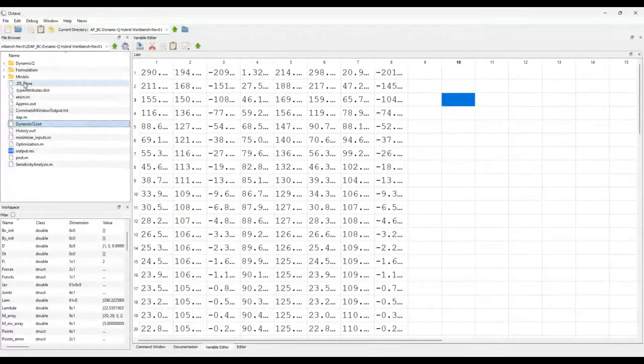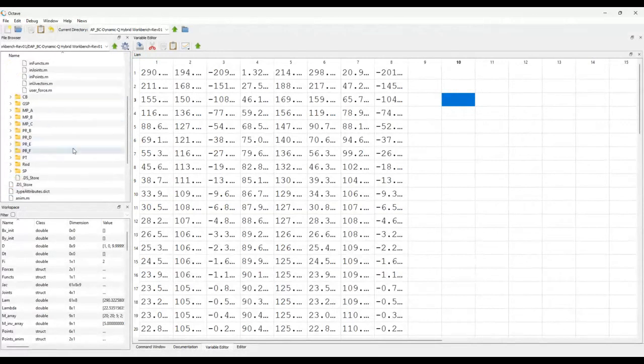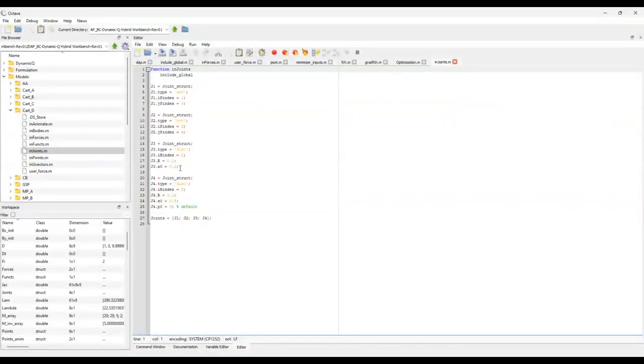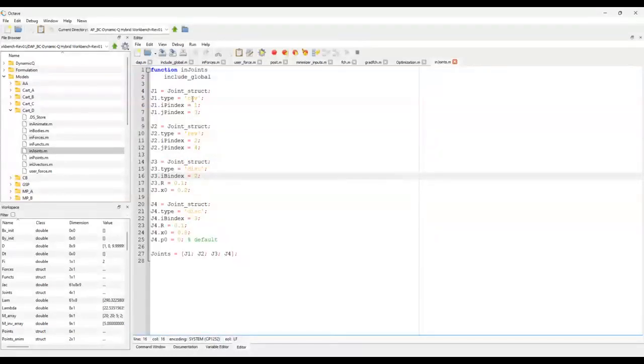Yeah. So if I'm not mistaken, I think for this problem, you actually have more joints because you also have those disks. So you define the revolute joints, which is basically between the car body and the wheel. But then on the wheel, because it's a disk, you want that no slip condition as well. So you're actually going to have more Lagrange multipliers which correspond to reaction forces, because that disk corresponds to the reaction forces at the point of contact. So in this case, we have a total of four joints.